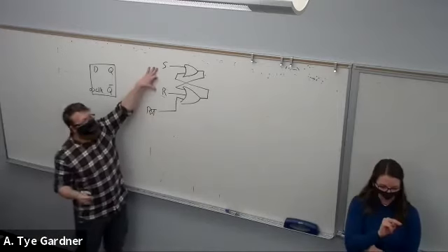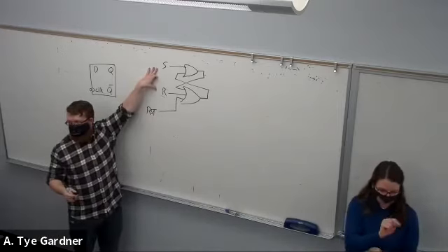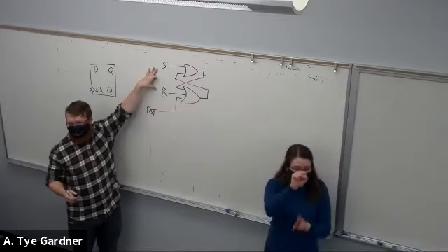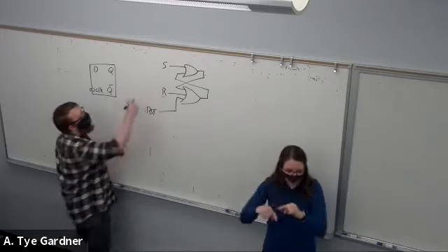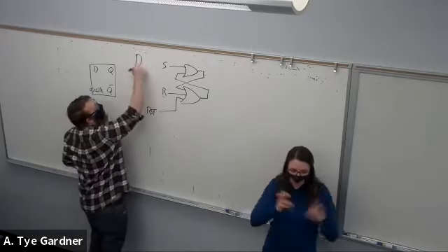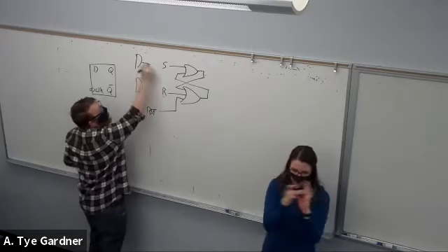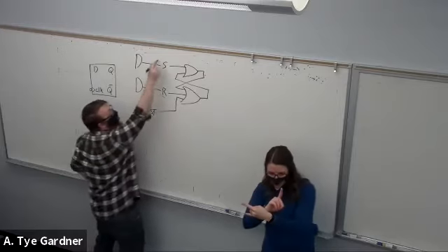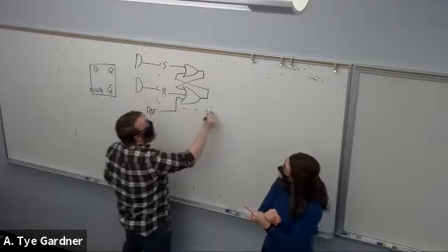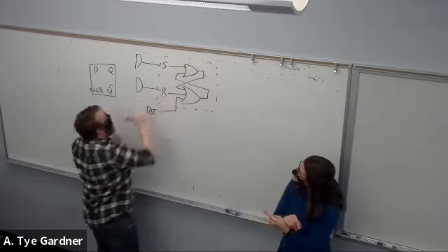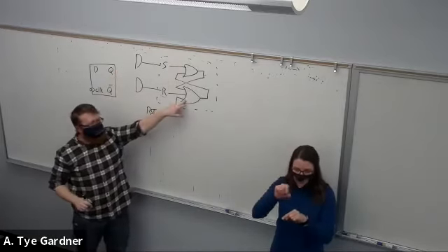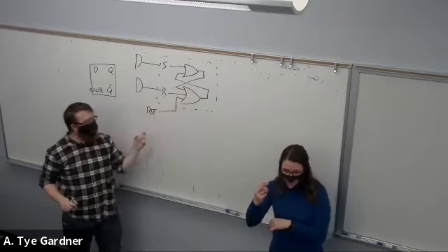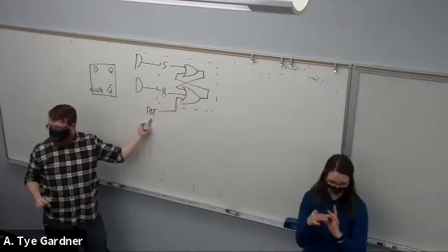Because S and R are getting tied into those AND gates, they can't really be used as the reset, since they're tied to AND gates out here, where this is the SR latch. So these two AND gates feed in, and by adding one extra pin, we have a global reset that we can then use.